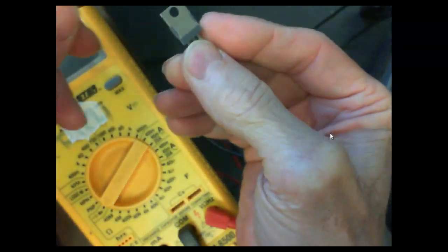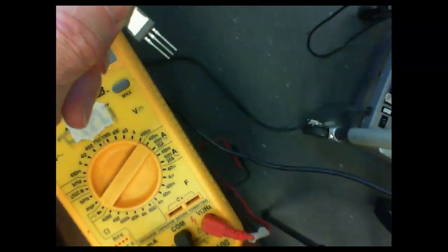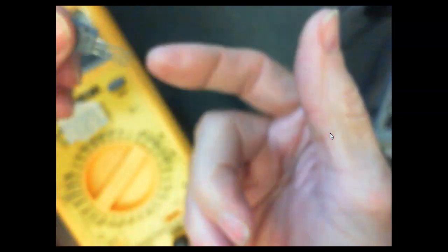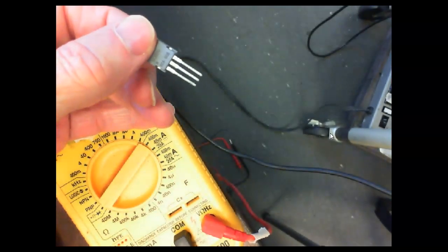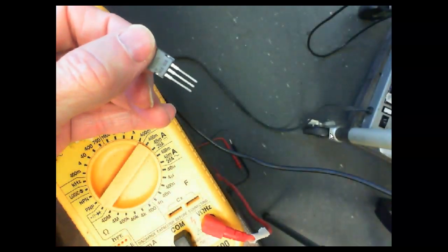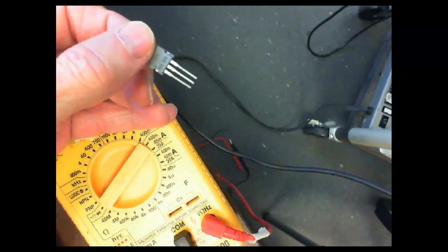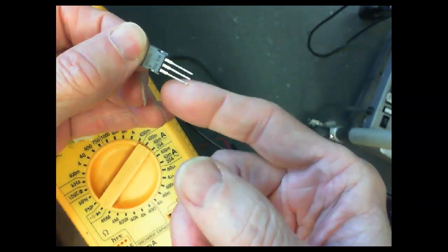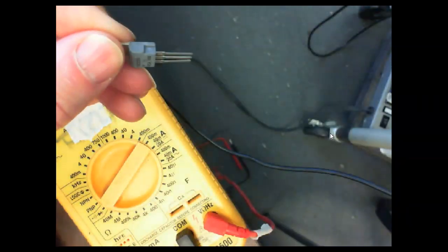So I could take an ohm meter and put it right here and start touching these three leads. Then I can find the collector. By the way, on these three terminal devices, the emitter doesn't necessarily have to be in the center. The base doesn't necessarily have to be in the center, even though it's in the center of the diagram. So we'll show y'all in a minute how you can actually identify these leads and check a transistor with an ohm meter on the diode set.